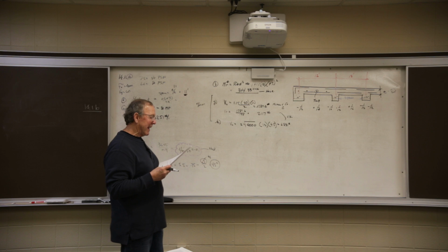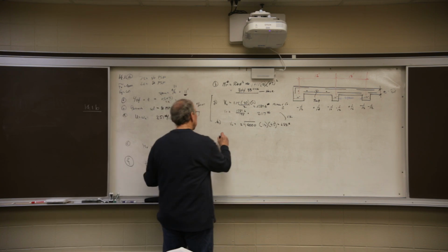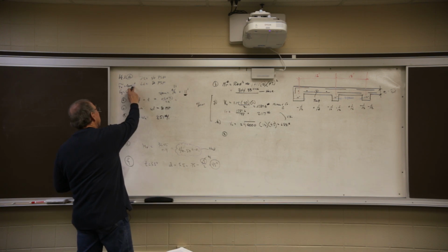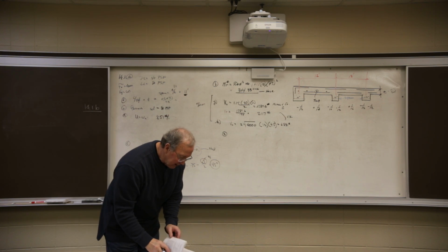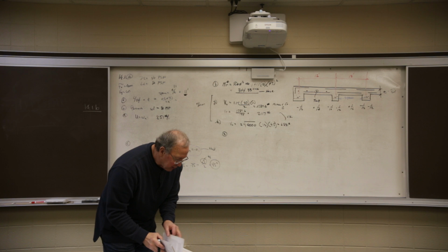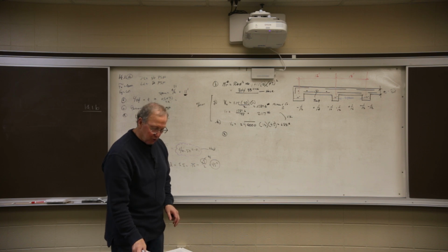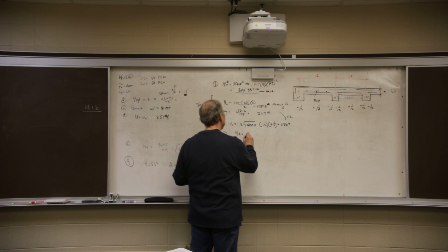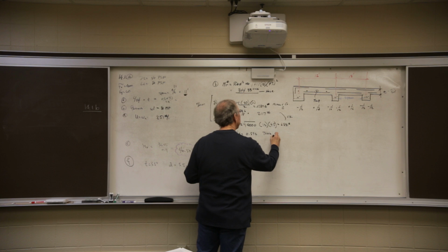Okay, determine AD for the balance section. So I'm going to go to the table, and I'm going to look up concrete and steel of 4,000 and 60 and get myself a value for AD. Page 423. 60 and 4, 0.592. AD table, page 423.